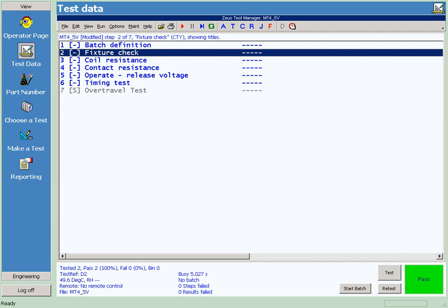This session will look at how standard relay tests can be extended to perform advanced assessment of more complex parameters on relay devices, such as contact over travel. It will concentrate on looking at a test that Applied Relay Testing have produced called the magnetic circuit test, which can be used to gain an insight into the contact over travel of a relay without needing to open the relay up or inspect it. This test can be done completely electronically.